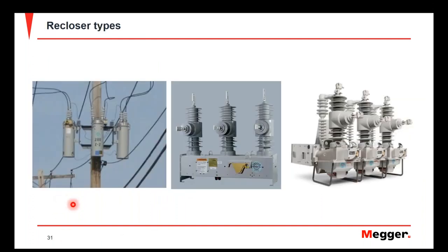So here are some different recloser types. We kind of mentioned earlier that we have single phase and 3-phase type of reclosers. Now, this first example here is of 3 single phase reclosers. And typically the application that we see for these is for a system that supplies a lot of single phase loads.